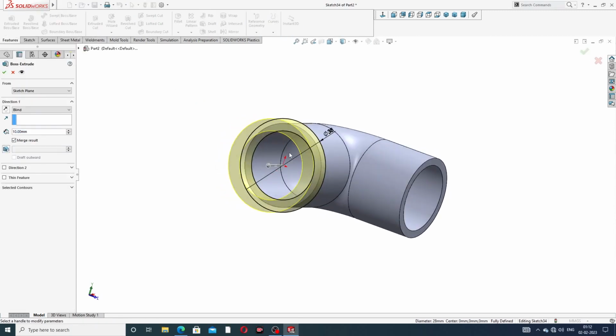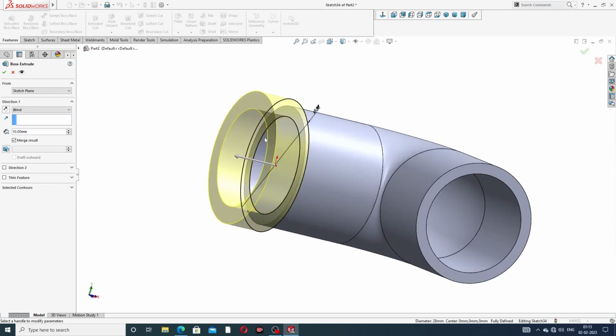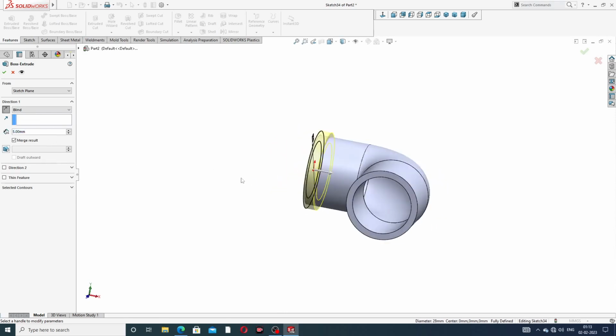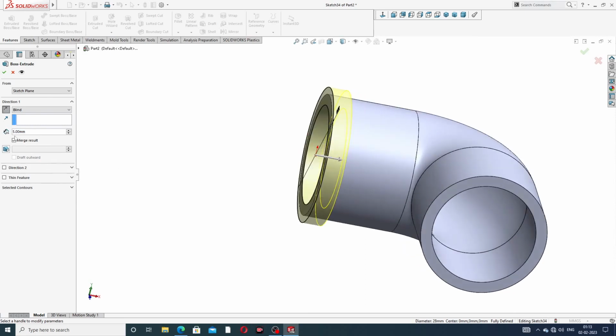This is open, and do not use this inward fillet. Then this is closed. Okay. This edge is also selected here, and this is a 5 millimeter thickness, and direction is inward. Okay, this is correct. And also change here, 6 millimeter, 6.2 is better, and direction inward is correct.